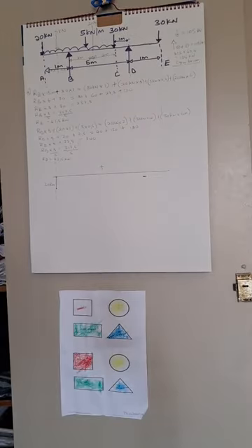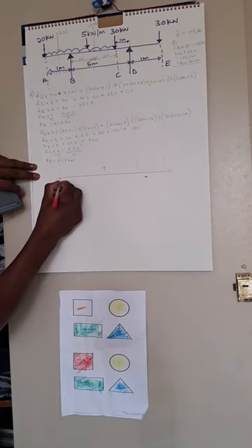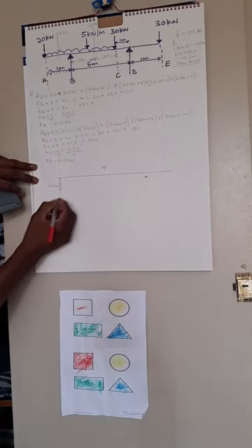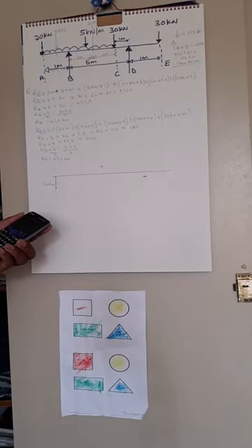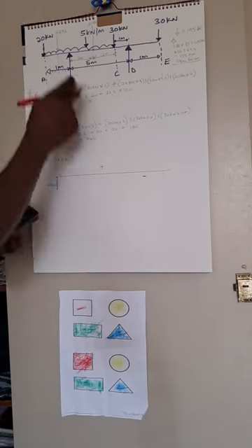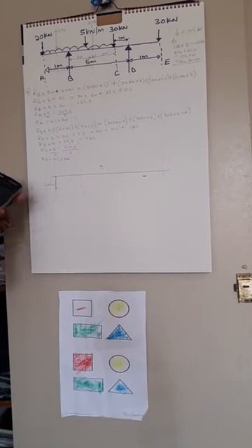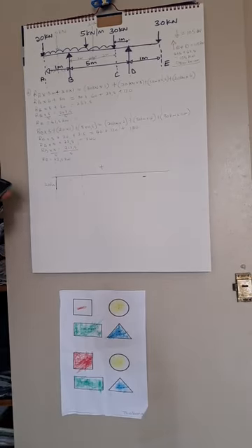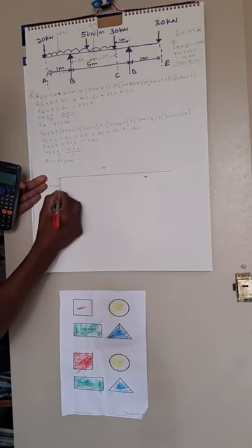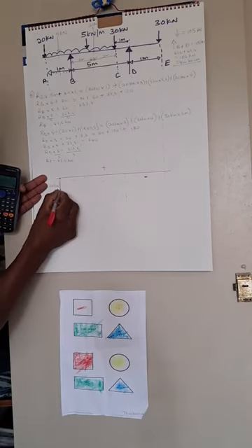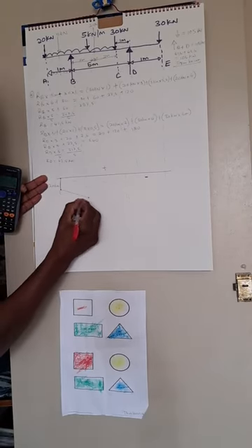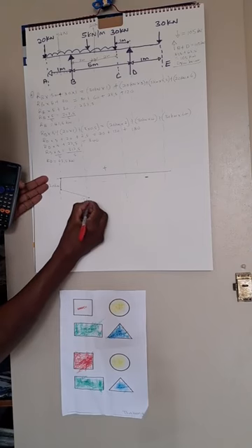Okay, so I managed to get a pen. So when we draw our shear force, we've drawn a line going downward to this point of minus 20 kilonewtons. So minus 20 minus 5. Because here we don't join a straight line because it's an area covered by a UDL. So we slope joining the second force. So we have minus 25 kilonewtons.